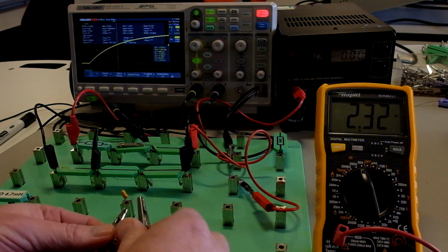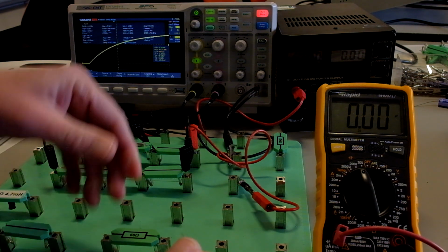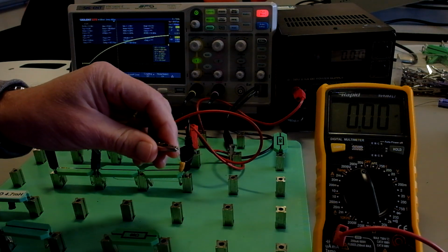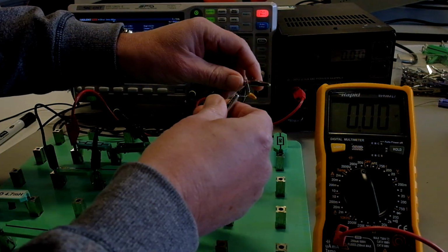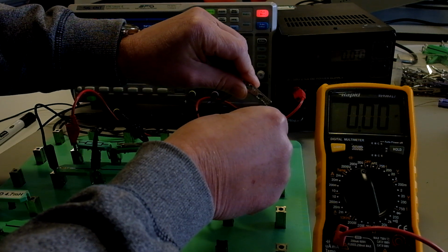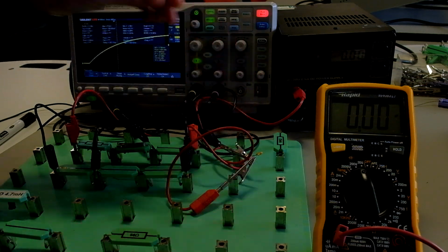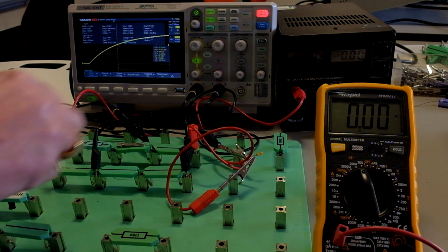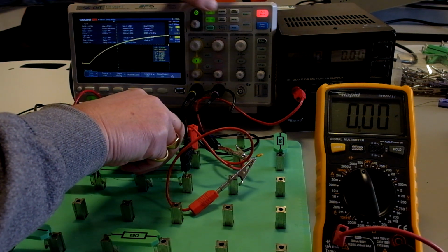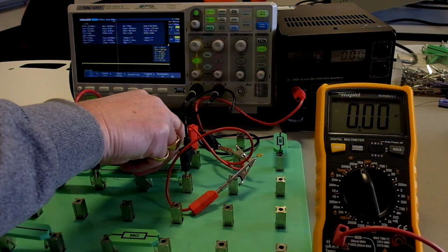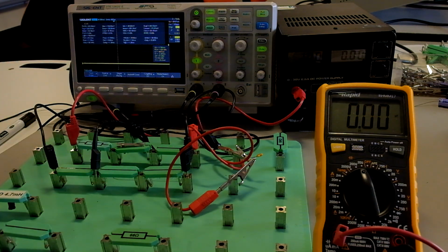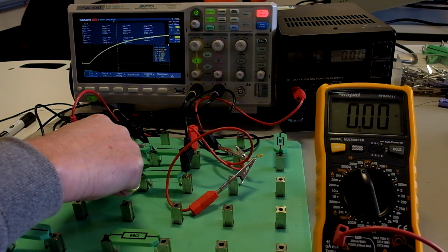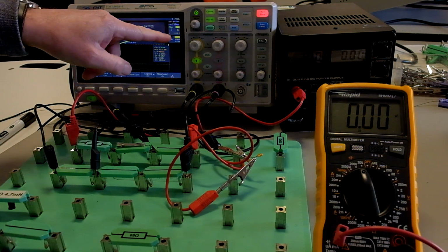Remove these out the way. Let us disconnect that capacitor from there. Let us connect the capacitor into the circuit like so. Let us discharge the capacitor just to make sure that it's fully discharged. Put that on auto. It's fully discharged, 0 volts there. We put it on single and then we close the switch and we're charging it up to 10 volts.